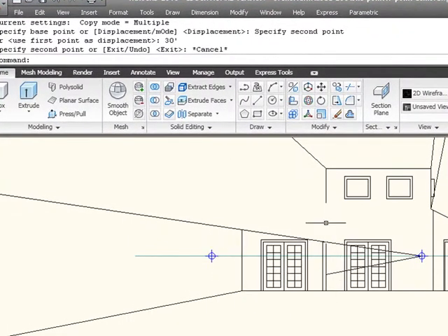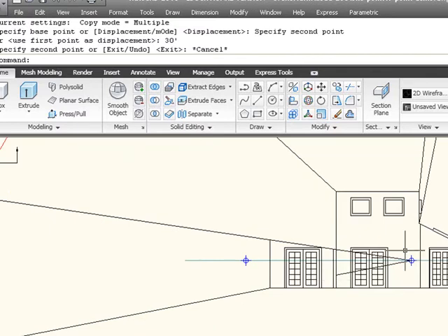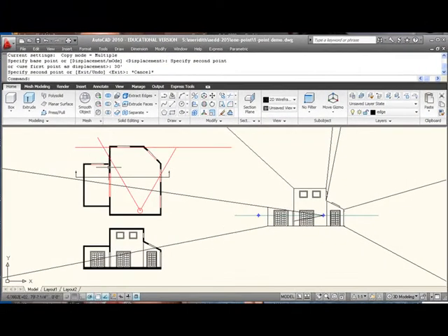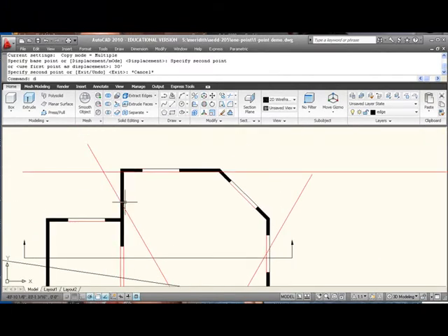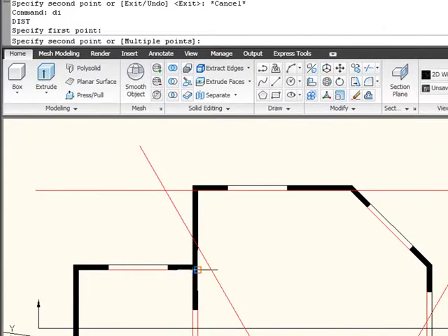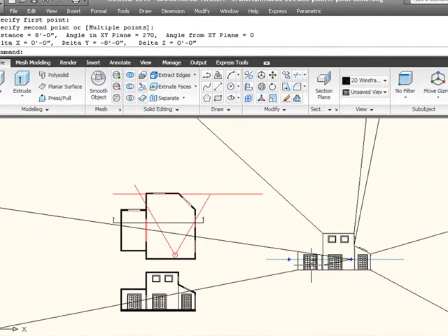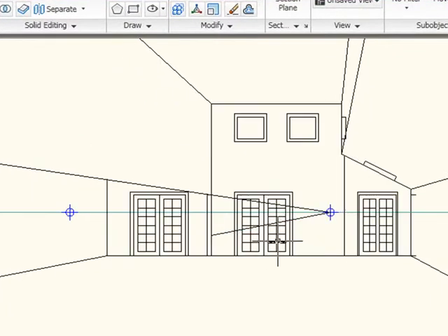Now that diagonal measuring point shouldn't go through this surface, because remember this surface we're going to end up having to make an adjustment here, because this right now looks like this is all on one plane. But remember that this surface here is actually in front of this plane here by this distance, 8 feet. So that's going to end up being pulled forward, and we're going to make that adjustment after we do this diagonal measuring point. So this is at 30 feet.